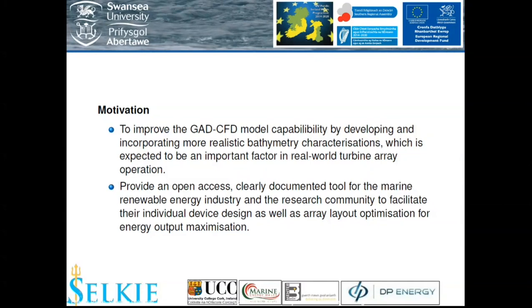Also reported are foil lift and drag coefficients and their variation with thickness, surface roughness, and Reynolds number, which is necessary for the proper characterization of the whole rotor.